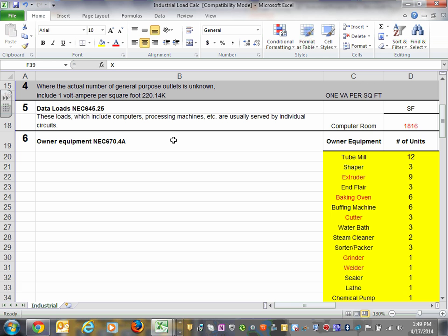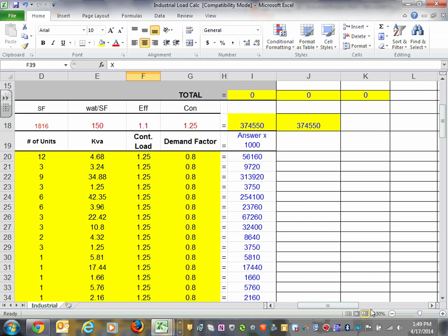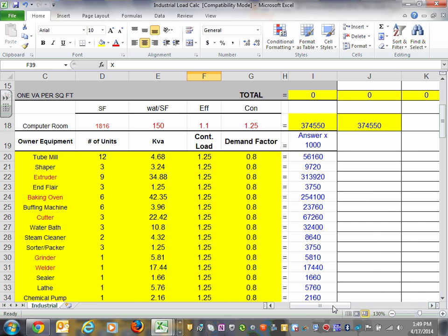So I don't know if you guys size data centers, but what you can do is what we have done. There are two methods: the square foot method and the rack method. The square foot method, you allocate a volt-amp based on the servers that you're using for the data center, and you multiply it by the square foot of the data center, call it a day. And I believe we're moving more towards a rack method. So every rack will have 5 kW or kVA equivalent. So 5 kVA for every rack. Tell me how many racks you have in this data center, multiply them by 5. You get this information from your data engineers and the servers they design.